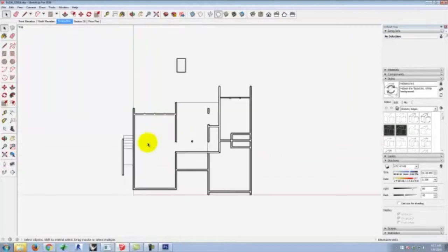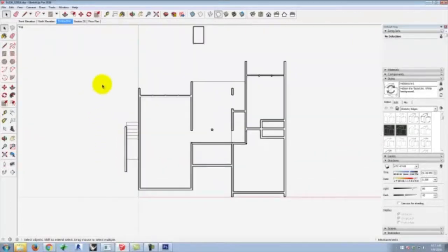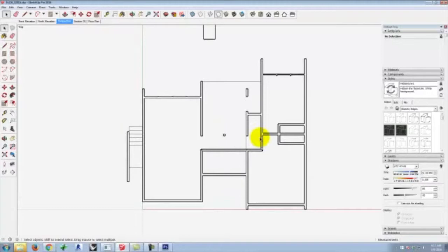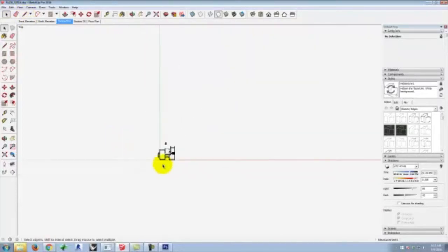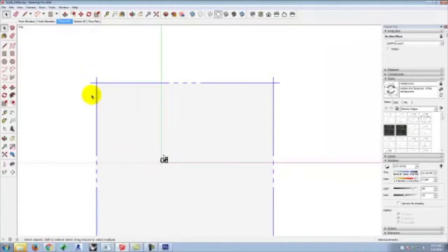So let me zoom back in. And once I'm zoomed in to look at my building, I'm going to go through the same process that we've been doing with my exports. But there's a couple things that are really important when you're dealing with exporting this essentially plan/section view. And that is that there's something called the section plane, which is this giant object here that's slicing my building.